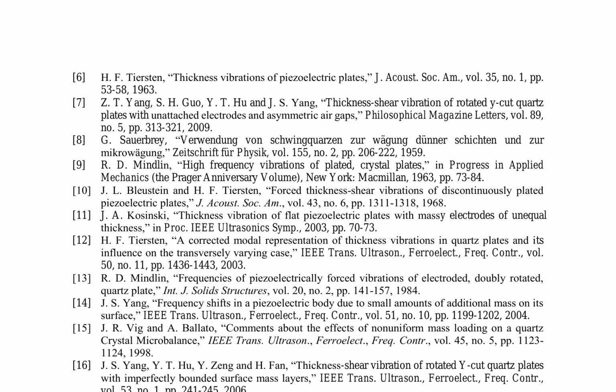The present work aims to derive a more accurate and comprehensive mathematical model, incorporating the effects of electrode thickness on the vibration characteristics of these plates. The researchers employed a variational approach, utilizing the Hamiltonian principle, to formulate the governing equations for the thickness shear vibration of the piezoelectric plates. The resulting equations were then solved using a perturbation method, which allowed for the extraction of the vibration frequencies and mode shapes.